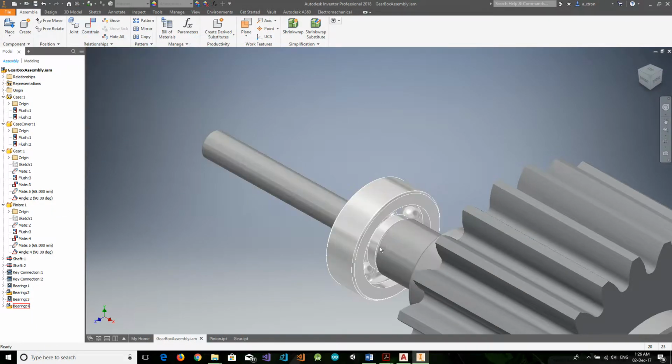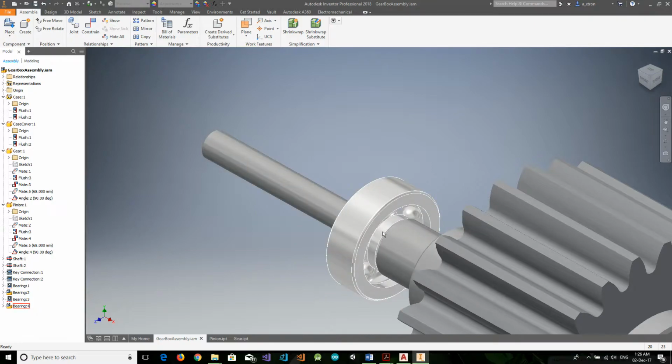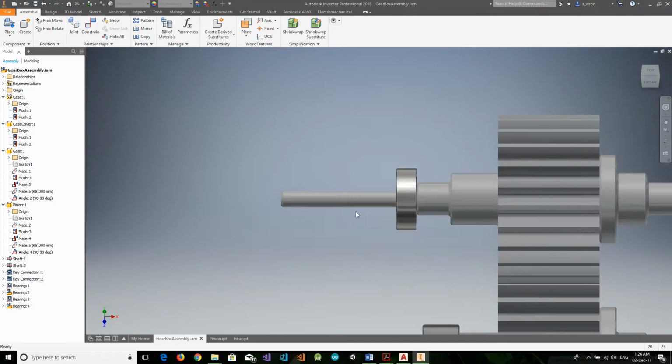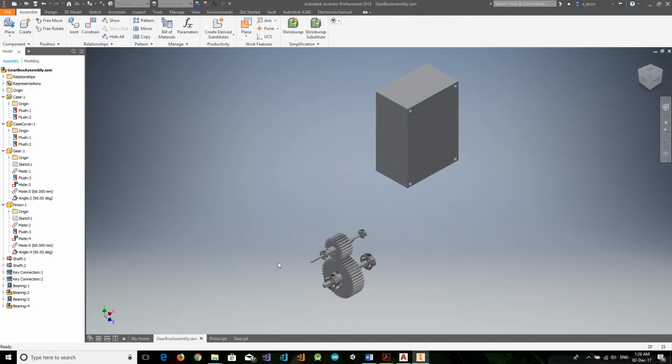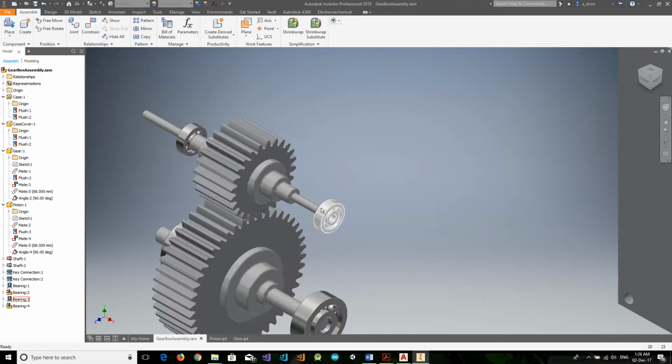So the idea of the shoulder we created is so the bearing, the inner diameter of the bearing can rest on, because both will be rotating. The rotation should not be linked together. So if this surface was in contact with the bigger surface, we might have some power loss that we can avoid. So we can have a better look from this side.